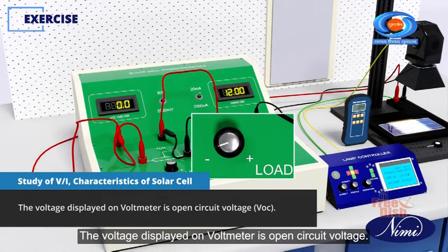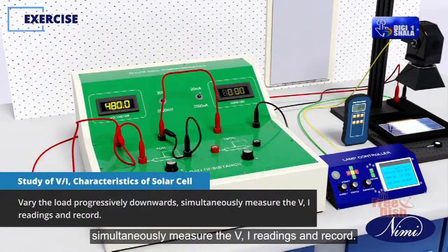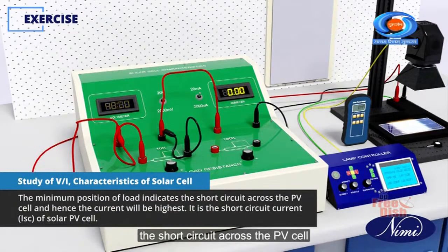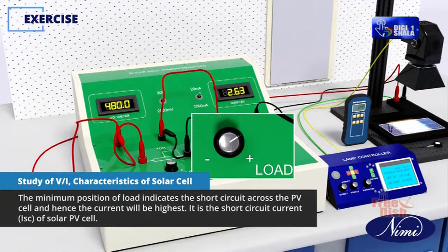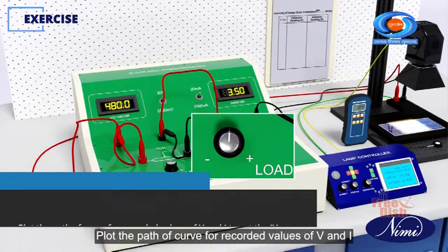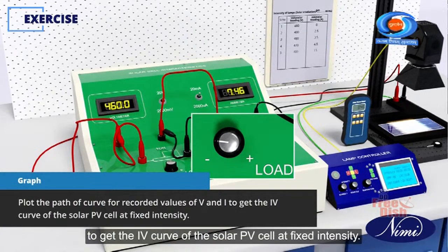The voltage displayed on voltmeter is open circuit voltage. Vary the load progressively downwards. Simultaneously measure the VI readings and record. The minimum position of load indicates the short circuit across the PV cell and hence the current will be highest. It is the short circuit current of solar PV cell. Plot the path of curve for recorded values of V and I to get the IV curve of the solar PV cell at fixed intensity.